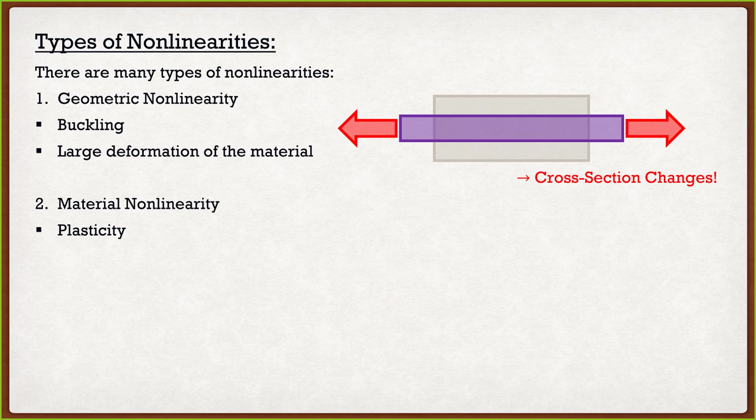which basically means that at some point in the material, once I start stretching it, it's going to have plastic deformation, or basically irreversible deformation. If something is elastic, I can stretch it, and when I let go, it's going to return back to the original position. When something enters the plastic region, I stretch it so it's plastic now. When I let go, it's not going to return to the original position. It's going to have some residual strains. So that's one of the first ones.